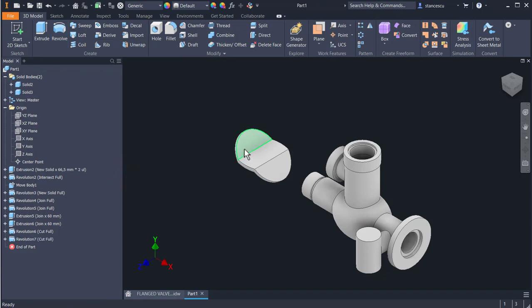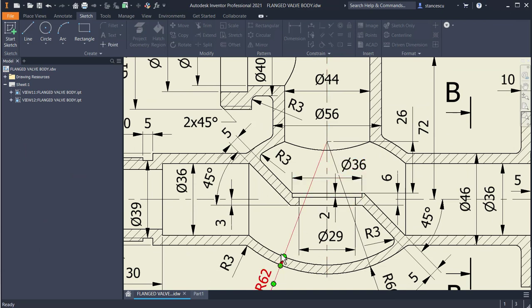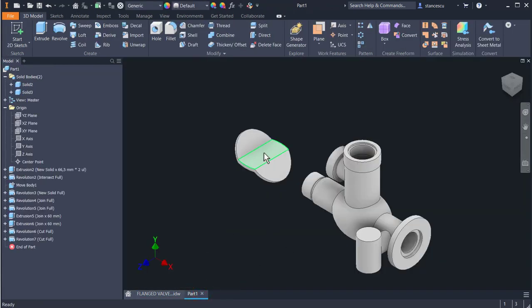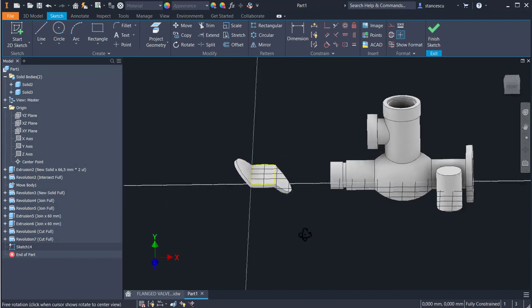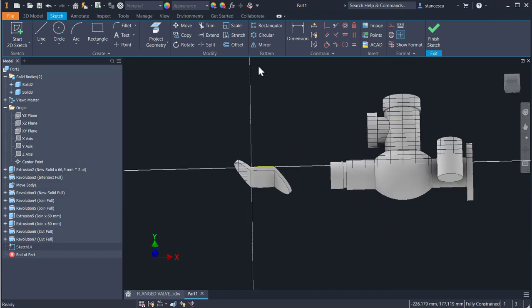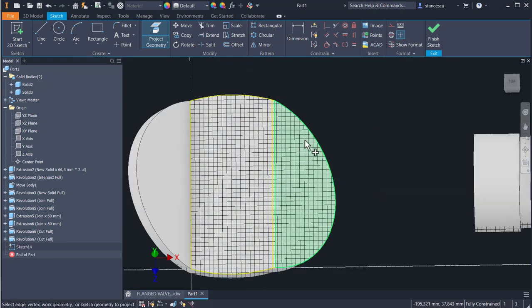Now we can move this inside, but let me create here this counterbore with 2 diameters and so on. I have to place it on the center, so I create a sketch by projecting this line up. Yes, you see there are 2 lines here.